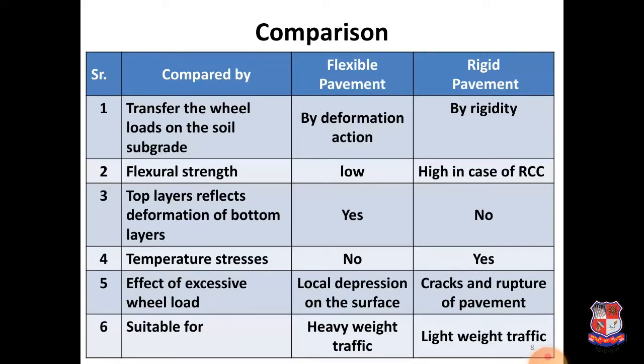deformation body, and the different layers of flexible pavement are deformed, and in this deformation action the wheel loads are absorbed in the layers of flexible pavement and transferred into the ground. In rigid pavement, the wheel loads are transferred on the soil subgrade by rigidity.